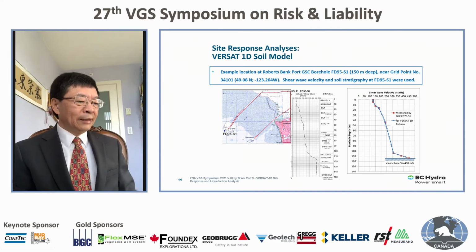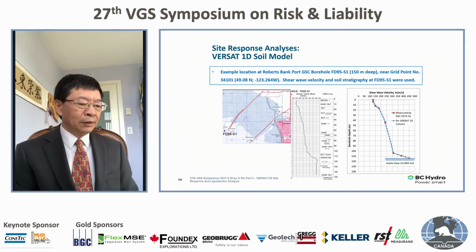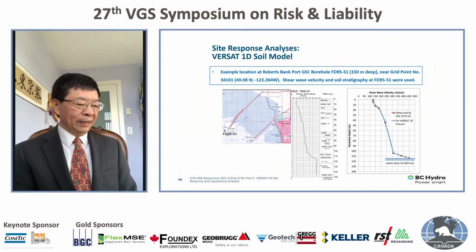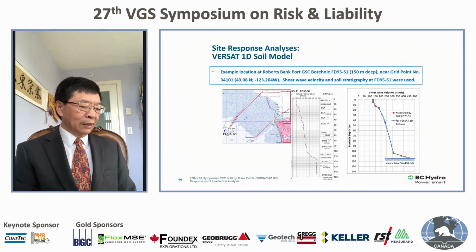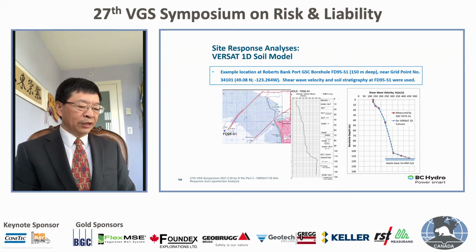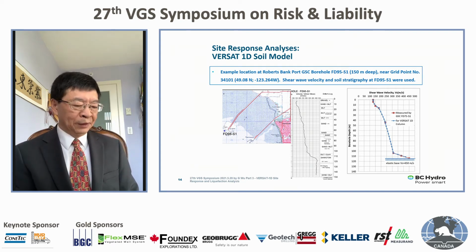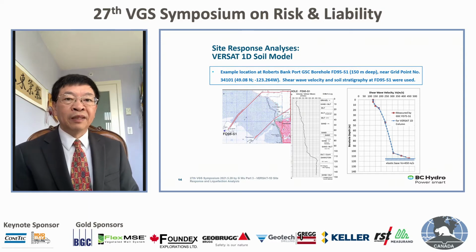So in this second example for the PSTA method, I'm going to continue using the 2017 model, which I presented in the VGS seminar. The left figure shows the location of this drill hole that was done by GSC, drilled as part of the earthquake hazard study. It was drilled to 150 meters depth with a measurement of shear wave velocities all along. So I thought that would be a good site to do the study on the PSTA method and also on the effect of elastic base on ground motions.